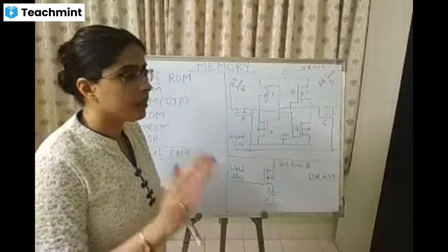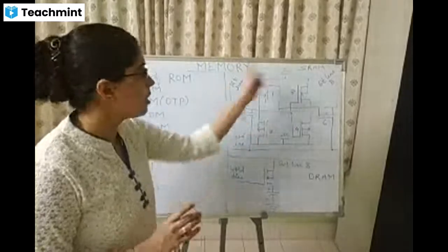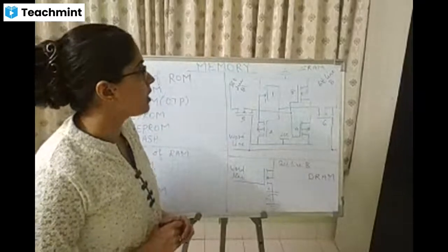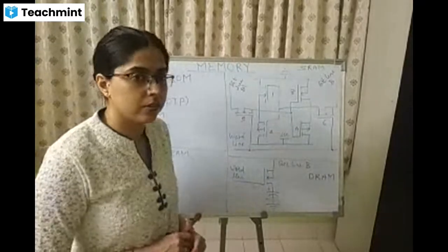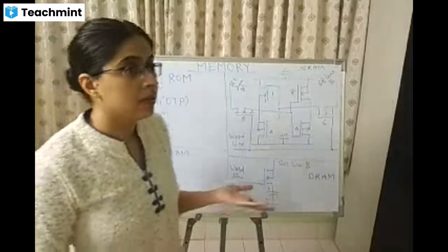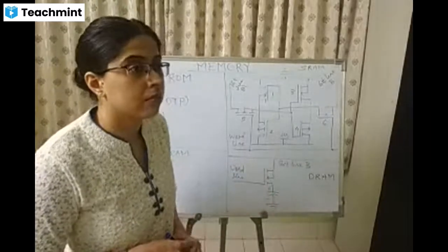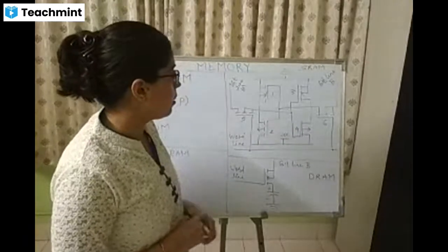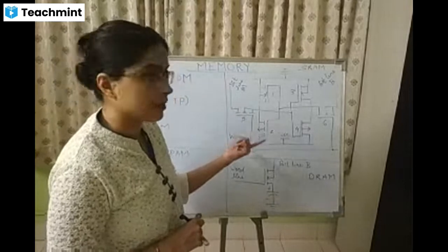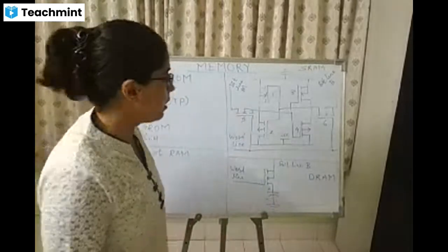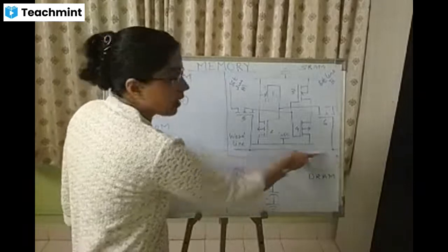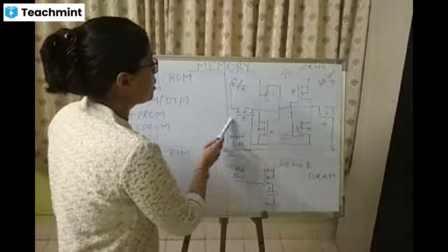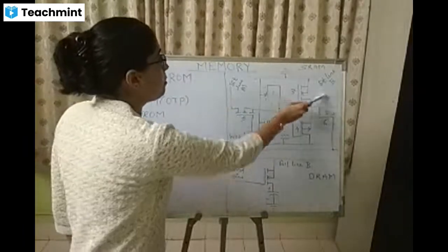Every cell has 6 MOSFETs inside it. This whole diagram is a picture of a single memory cell, and a single memory cell of an SRAM has 6 MOSFETs inside it. So you can imagine the number of cells on a silicon chip. If you want to read or write the contents of this SRAM, reading and writing is controlled by this word line. This is connected to these two MOSFETs, which in turn control the bit lines B bar and B.